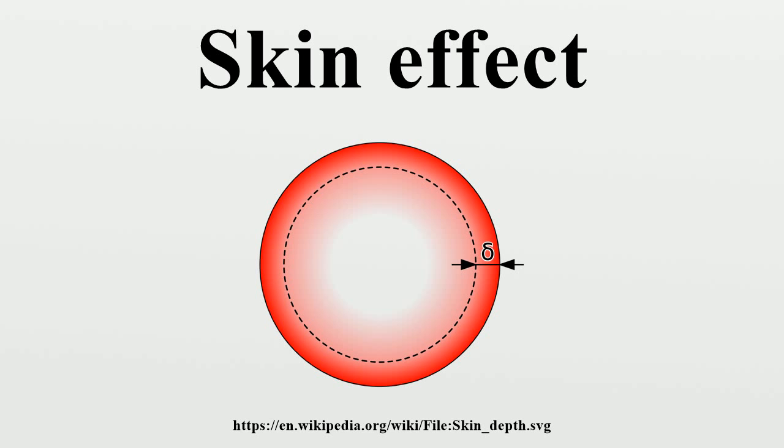In contrast, lead is a relatively poor conductor with a resistivity of about 2 times 10⁻⁷ ohm meters, about 9 times that of gold. Its skin depth at 50 Hz is likewise found to be about 33 mm, or about 3 times that of gold.